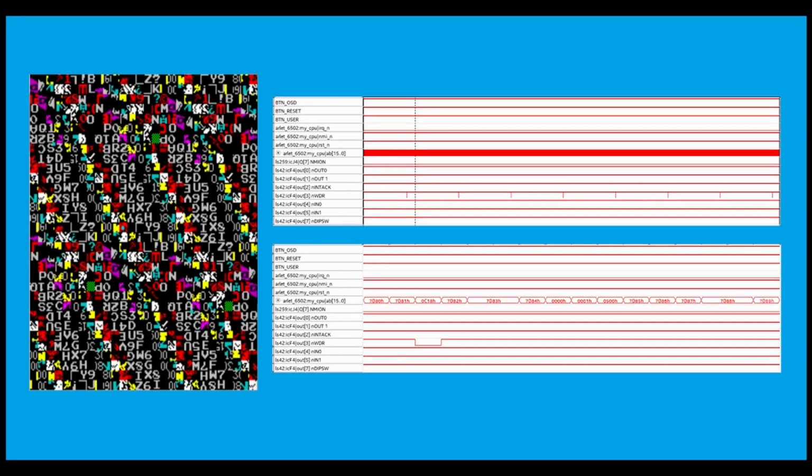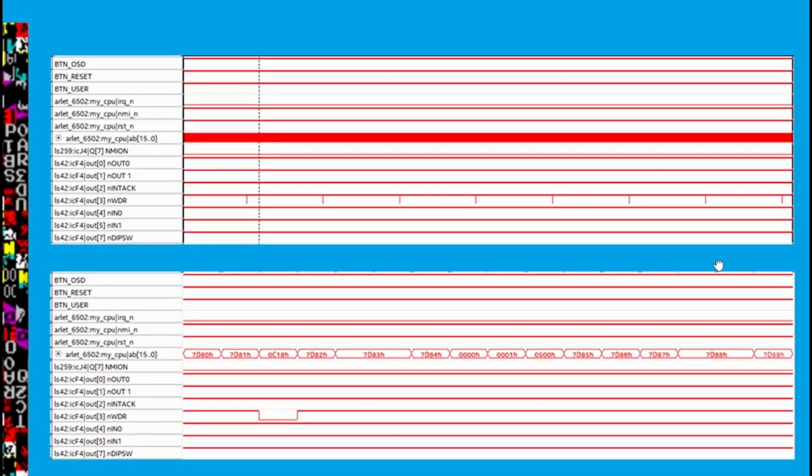To understand how the game works, we'll take a look at each state to see what the interrupts are doing and what the CPU is doing. To do this, I've used Signal Tap to record the state of specific pins in the FPGA design. I've clocked it as Phi2, which is the CPU clock speed. Therefore, we get a nice view of the CPU address that it's looking at.